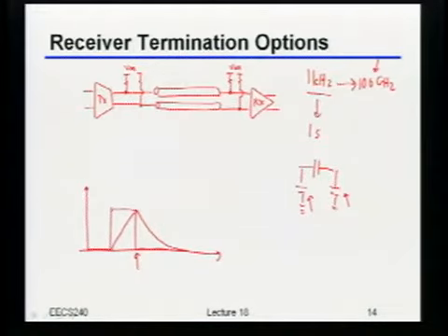Okay? So, just to be clear, everybody, that's the limits of integration you should use in SPICE. Okay? So 1 kilohertz to 100 gig. So whether or not flicker noise is important, that's for you to figure out.